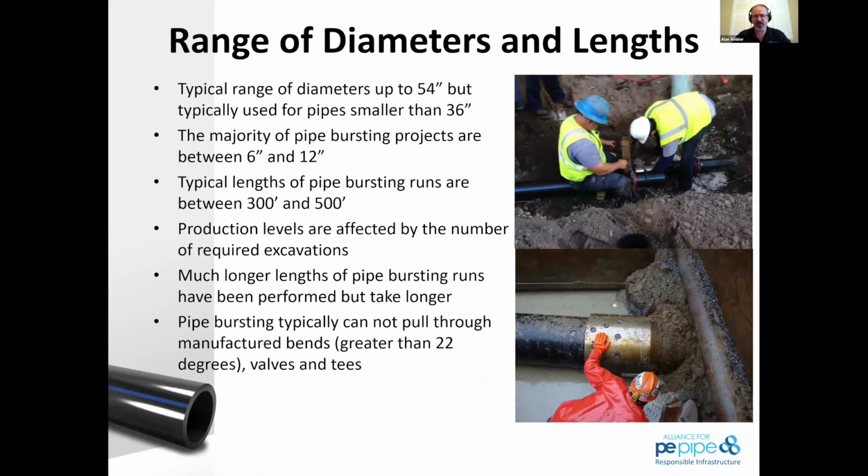So that's a very interesting difference. We were asked a quick question about pneumatic and static installation times. Once the actual pipe bursting process starts, sometimes those installation times are very, very similar. It's a lot of the prep work that takes more of the time itself. A big impact is just the length of what you're doing. Depth and also soil conditions would make a big difference there. So great questions, and I love to see that they're coming through here. We'll move on to the very next one.